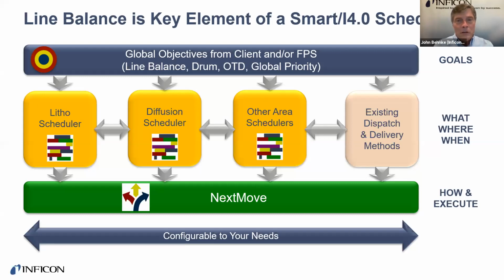It's very important that you've created a model and an understanding of the non-linearity such that you can then feed to the other little local optimization engines what you would like to prioritize. So if you're creating a scheduler on the global objectives, and we see litho on the left here, litho drives linearity. We just discussed that because it's reentrant. You need to determine and tell that scheduler which layers are more important to improve linearity. That's the way this works.